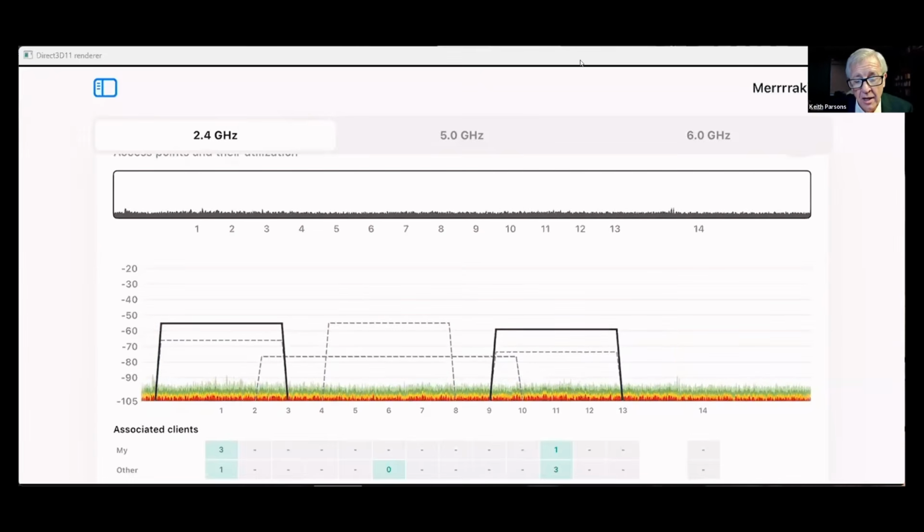What I use is a grid. You cut the room into 4 chunks, go to each of the 4 chunks and measure the RF there. Then you cut the highest one into 4 more, and you work your way down to find it, especially when they're not constantly on. It sometimes takes hours and hours to track something down physically, because you don't know what's triggering it. So you have to wait in each of those quadrants, and then go to the smaller quadrant and do it again. So it's just a different technique.